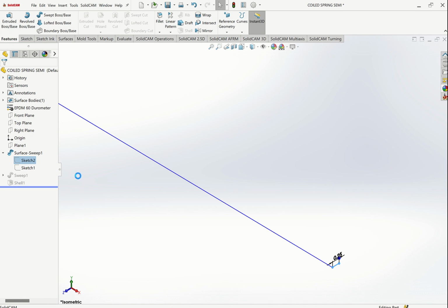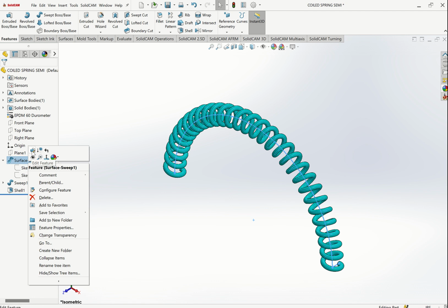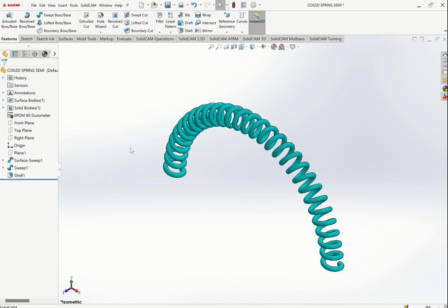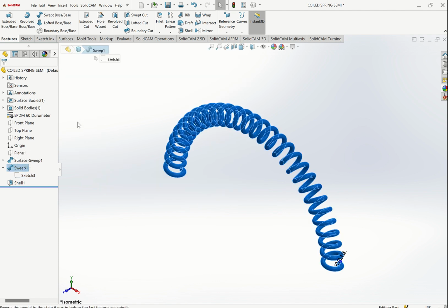Then from there, we made a surface sweep. So surface sweep, maybe we can add the surface sweep. We put a surface sweep, this being the path, and that being the profile. You see the profile, that's one. Then the path is this one. From there, out of this surface, we create a simple sketch. This sketch at the far corner from the right plane, the far corner here. Then from there, we went ahead to use the feature sweep command.